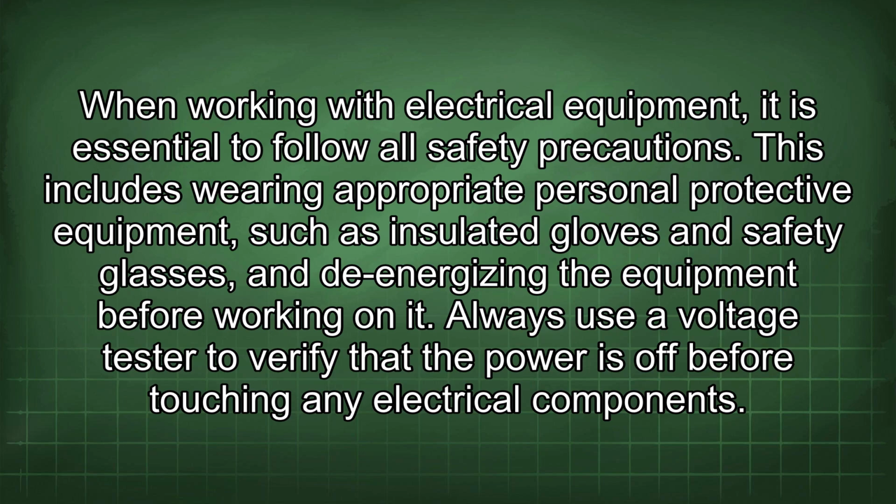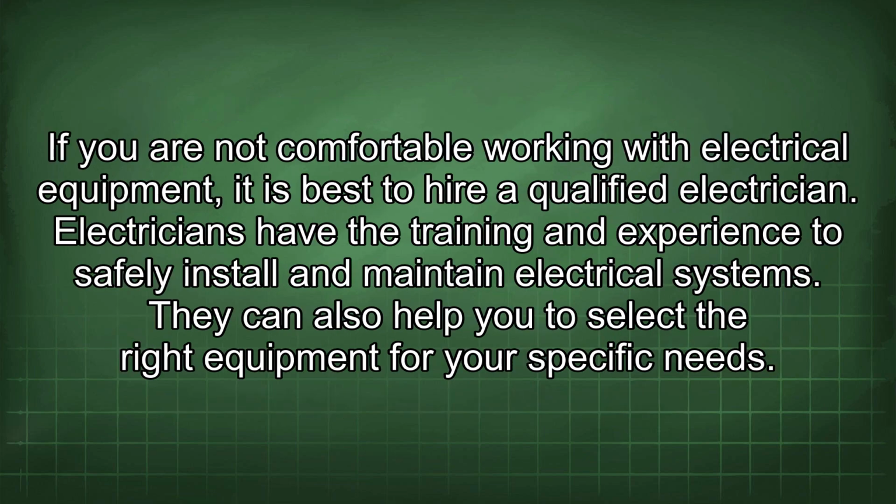When working with electrical equipment, it is essential to follow all safety precautions. This includes wearing appropriate personal protective equipment, such as insulated gloves and safety glasses, and de-energizing the equipment before working on it. Always use a voltage tester to verify that the power is off before touching any electrical components. If you are not comfortable working with electrical equipment, it is best to hire a qualified electrician. Electricians have the training and experience to safely install and maintain electrical systems. They can also help you to select the right equipment for your specific needs.